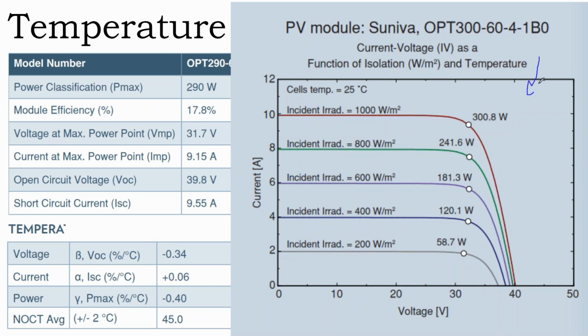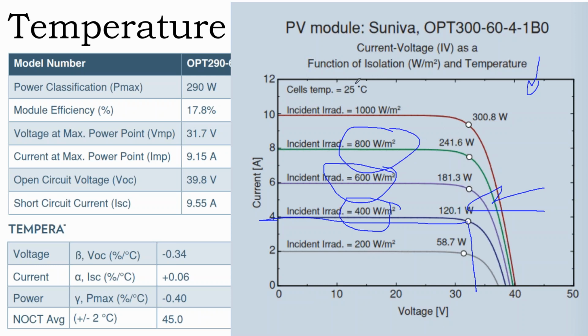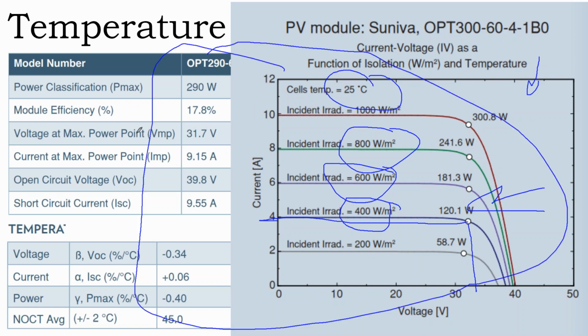So now we got a little chart that is really not that useful, other than just to understand the concepts. When they're talking about maximum power point, they're really talking about the module operating voltage, module operating amperage under normal operating conditions. And now we see a little bit more about array irradiance and how it appears on module spec sheets. And we understand that all of these values are deriving from a rather chilly environment. A 25°C rooftop temperature is kind of like a 55° Fahrenheit day outside.